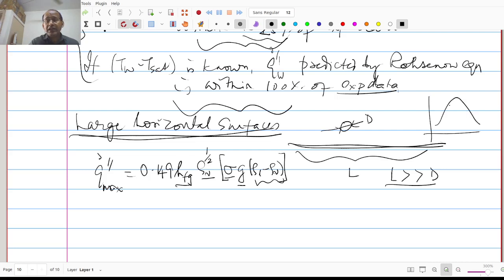If you have a look at the T-s diagram of this one, you have the liquid state here and the vapor state here at any given pressure. So this is the T-s diagram, and at any given pressure you have the T-s curve like this. This is for some particular value of pressure. Then here you will have a v_f, and here you'll have a v_g. Then v_f is 1 by rho_L and v_g is 1 by rho_V. Okay, so this is how you recognize these.